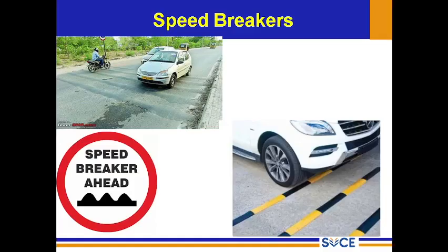Although it is known that humps contribute to speed reduction, the degree of the effect varies with the profile, height, gradient, slope, length and material used. Usually there are three types of speed breakers: circular hump, trapezoidal and sinusoidal hump. It depends upon the chord length, which varies from 12 meters to 113 meters. The IRC code book is available for this. IRC 99 can be referred to. Traffic calming devices and reverse speed breakers are also discussed. It can be referred to.